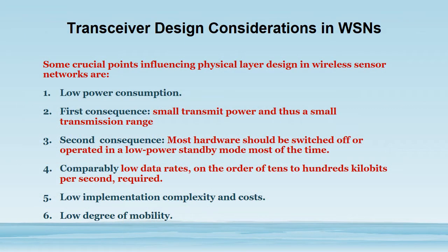Transceiver design considerations in wireless sensor network. Some of the major points influencing the design of the transceiver. The first one is low power consumption. So we have to design a transceiver that must consume very little power. Then only the lifetime of the node will increase. Otherwise it will die as soon as possible.